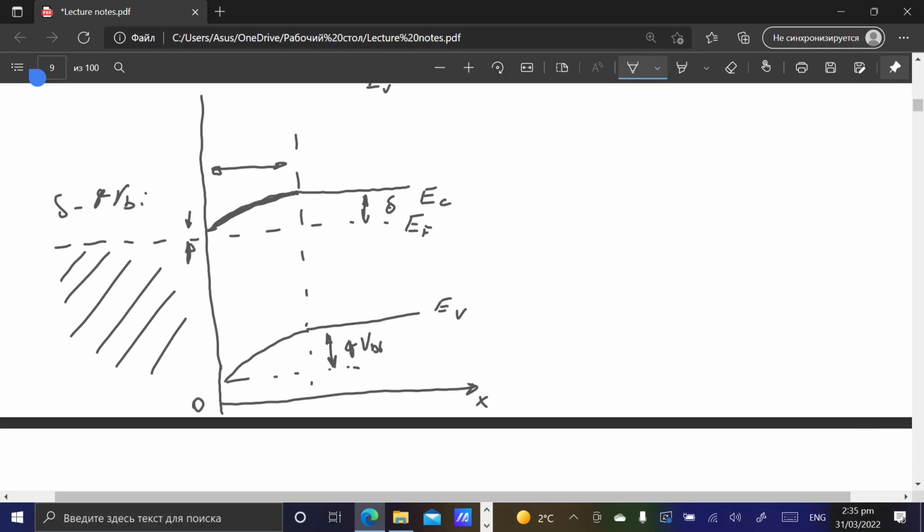Why don't we see a strong dependence of the thickness of this enriched region on external bias? Because the voltage drop happens over the larger resistance. So what is larger? If we have metal, we can neglect it, since metal is obviously very conductive. In the first case, we have a depletion region and neutral semiconductor. Neutral semiconductor possesses much higher conductivity than the depletion region.